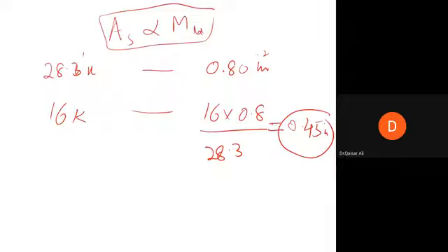For all the bending moments, you can now calculate the area of steel using this unit rule for the column strip as well as for the middle strip, because the thickness of the slab is uniform. So you can use the unit rule for any of the bending moments. And since effective d we have taken as the average effective d along both the directions, you can use this unit rule for the other direction as well.